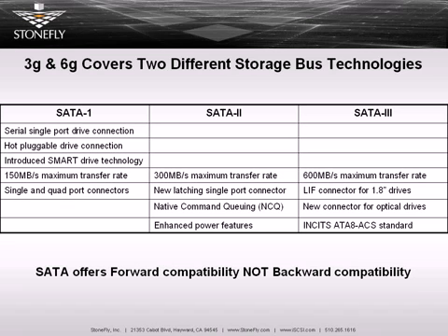And they added in new power features. The world is green. Green standby and spin down commands were added to the SATA 2 command set to enable control of drives when they're not being used, either by policy or by command. And just as a sidebar, the controller has to support these as well. You can have a green drive, but if you don't have a controller that supports it, you're not going to be able to use those features.